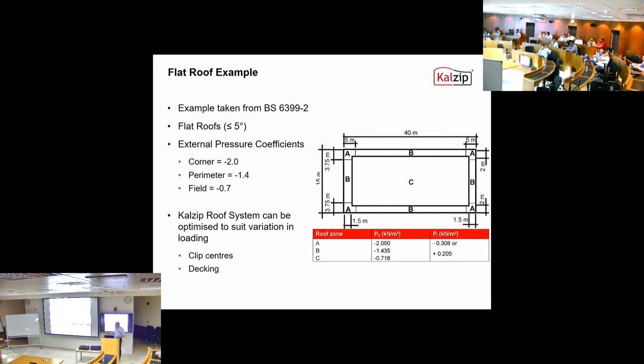So if you're on a structural deck, this is where you can put clip centers closer in the edges and at the eaves. In the middle, you can increase the clip centers, so that'll have an impact on your costs, on your installation time, and how the system is installed.